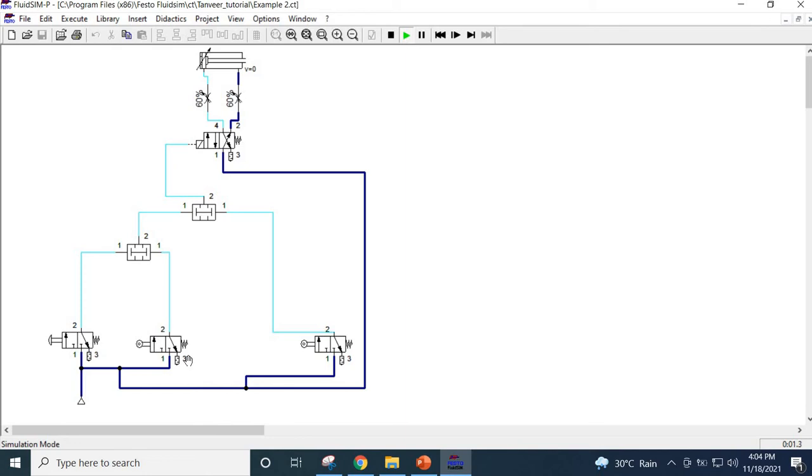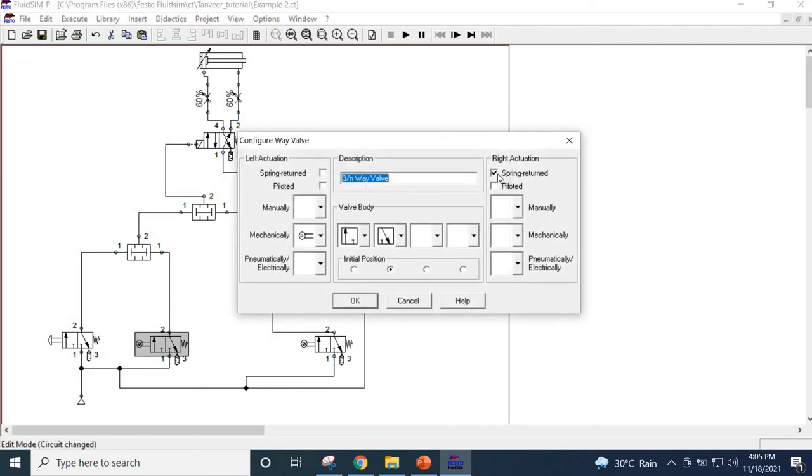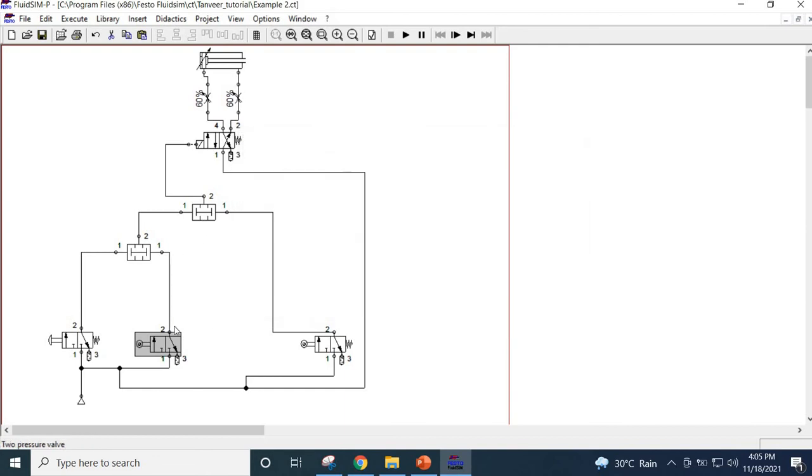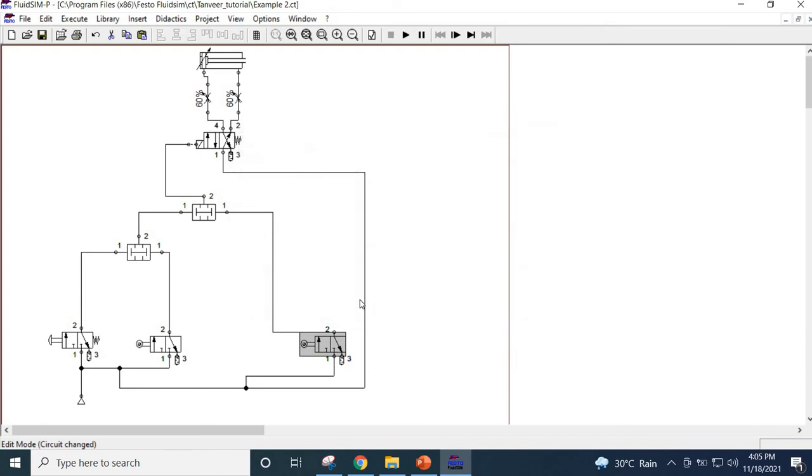Okay. So now, as you can see here, there is no pressure, so it is basically in the retracted position. Now I cannot really press this one and this one together, because if you press one and release, you cannot press the other simultaneously. So I stop here. For simulation purposes, I change it to not spring loaded, just a simple maintained contact type. The maintained contact is like a normal light switch. Once you press, it maintains the contact, and then you have to manually switch it back.